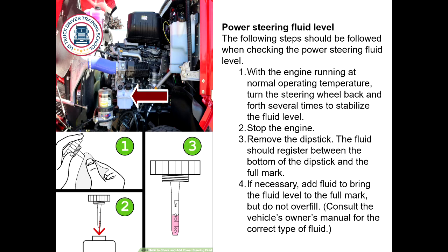The fluid should register between the bottom of the dipstick and the full mark. If necessary, add fluid to the full mark, but do not overfill. Consult your vehicle's owner's manual for the correct type of fluid.